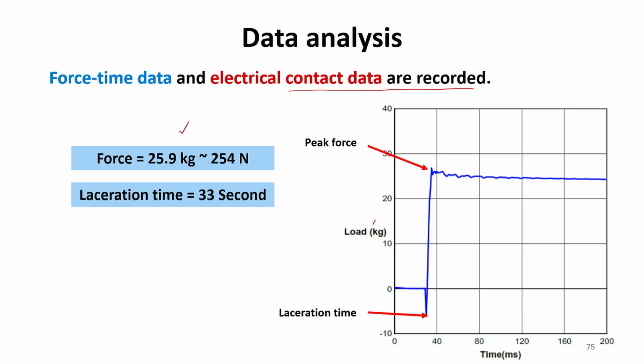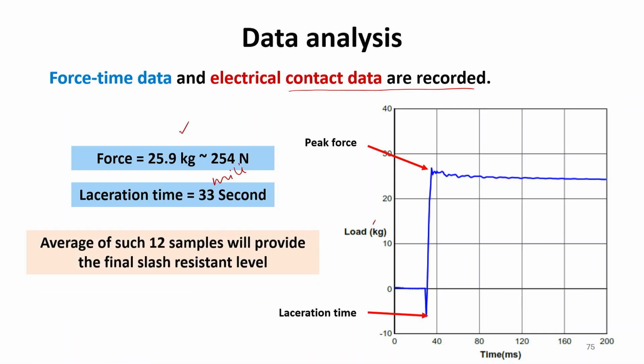The laceration time is 33 millisecond. The average of such 12 samples will provide the final slash resistance level.